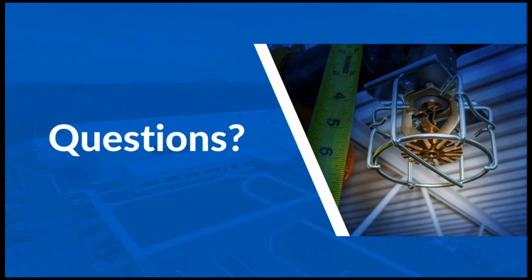Very good questions. Both those sprinklers, the attic sprinkler and the corridor sprinkler, have approvals from UL for light hazard occupancies. So the fact that you want to go into FM is sometimes okay. Like we've seen FM sort of say we don't have a sprinkler, so just use it. But when you talk about HC2, that ends up being really an equivalent to an ordinary hazard, and I don't see that really flying. And with the cable tunnel, I don't see that one either.